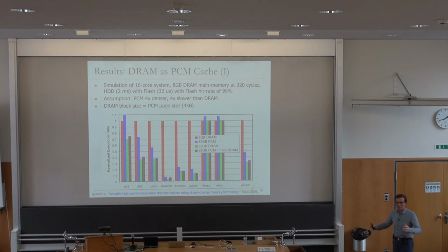In that case, of course, you buy a lot more performance, right? Well, we'll see how much. The assumptions are a little bit different. So we assumed, for example, phase change memory is, in terms of reads, 4x slower than DRAM, though that's similar. But for us, writes were asymmetric, which is really true in existing phase change memory systems. So we said writes are 12x slower. And this paper assumed that they're also 4x slower. That's okay. Basically, they're going to alleviate some of those writes with the DRAM.